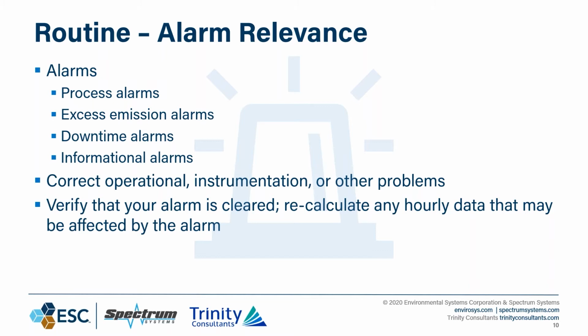As a very basic example, if you have an emission limit based on a 3-hour, 8-hour, or 24-hour rolling average, based on the exceedance of an analog value, an analog level, some number, then more than likely it would be to your advantage to know about that on an hourly basis, anytime you exceed that number, so that your operations or controls group can take action and mitigate any further exceedances from occurring. It's just an example.